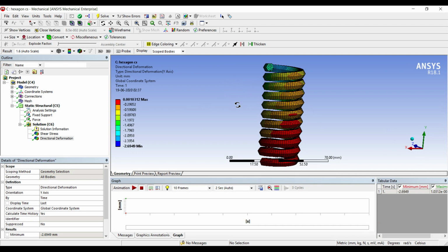So as the geometry becomes different, the number of turns will either increase or decrease based on the area that it is going to occupy. The two turns should not just merge into each other, otherwise the flexibility of the spring will be lost, because there should be some gap between both the turns so that the spring is able to compress and is able to absorb the shock.